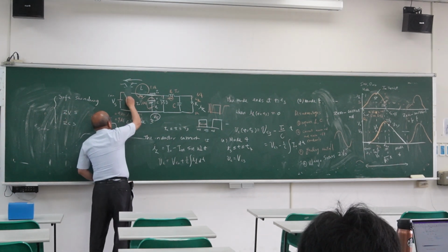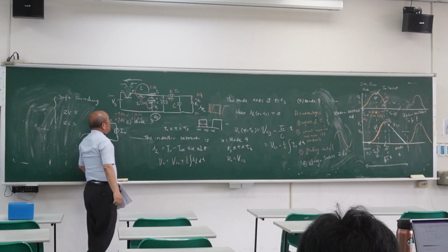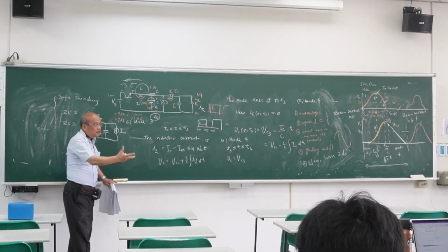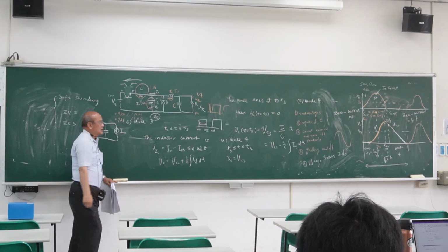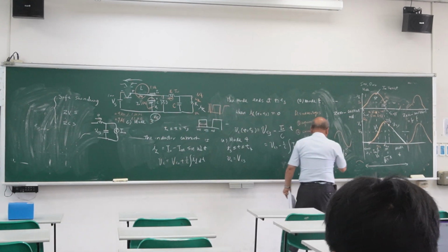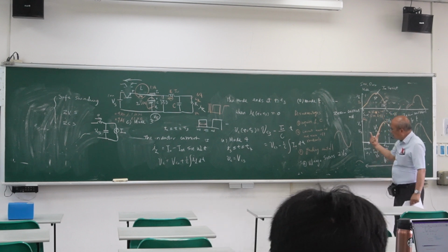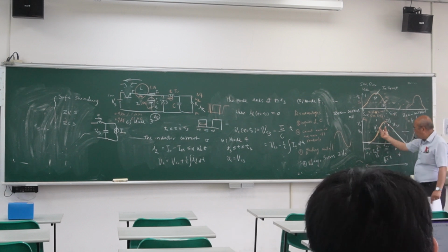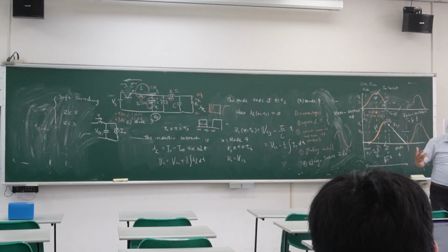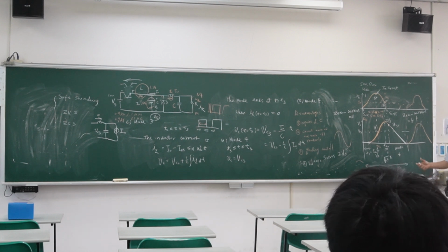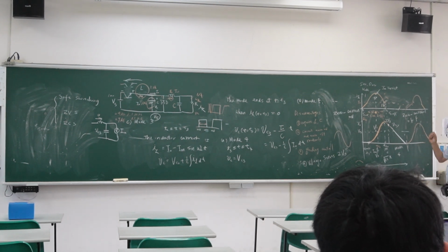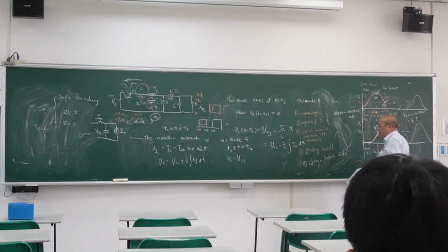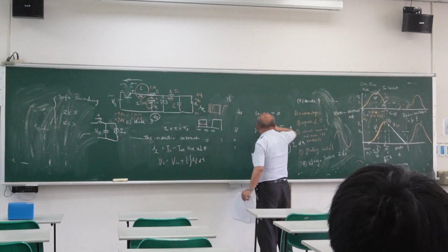So you have a device here. The device has voltage stress. Before it was 100, now it becomes 200, so the device becomes more expensive. So the voltage stress is increased. Also, your turn-on duty and turn-off duty are fixed. You cannot say I want to turn on 1% and turn off 99%. Impossible, right? So you have a minimal turn-on and a minimal turn-off. So this is the disadvantage. What is the advantage? What is your advantage?